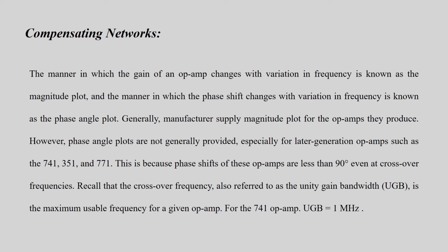The manner in which the gain of op-amp changes with variation in frequency is known as the magnitude plot, and the manner in which the phase shift changes with variation in frequency is known as the phase angle plot.